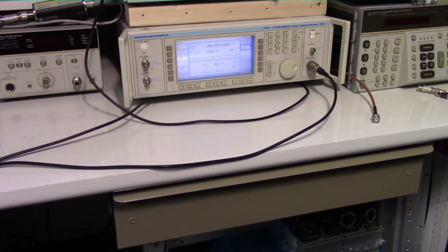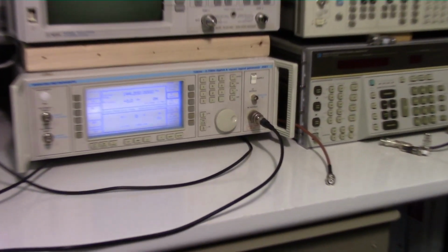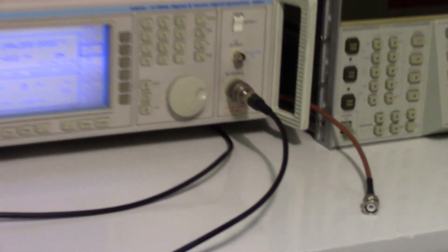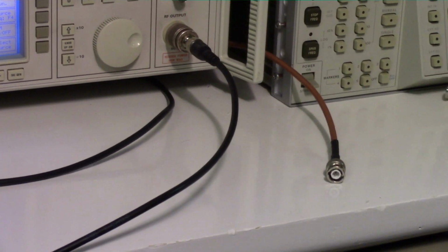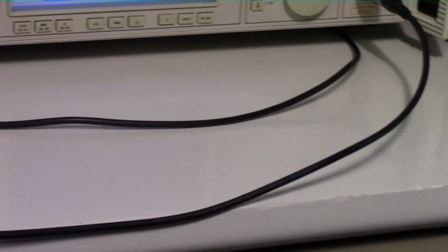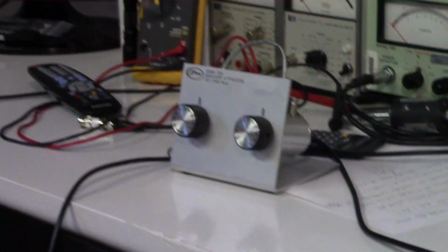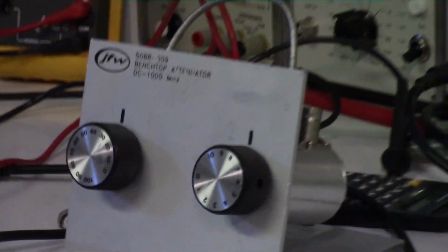What that really means is that if I had this signal generator set to a high level of, say, minus 40 or minus 50 dBm, and the shielding effectiveness was only 35 dB, it could be very easily coupled into the cable, blowing right past things like a step attenuator and ending up on the other side.